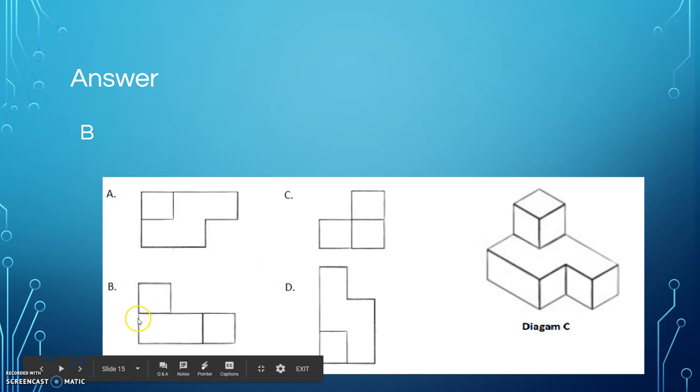So when I look at my views, view B over here has got the rectangle. So this surface here matches that surface. This one above, the square, matches this. And then this square to the side over here, where this edge is right next to, is right over here. So here's the square, here's the edge that you would see.